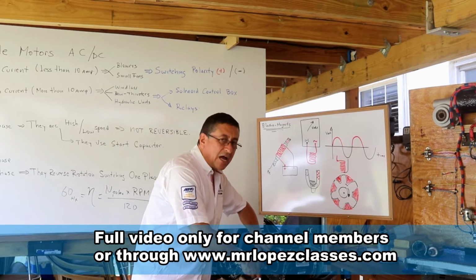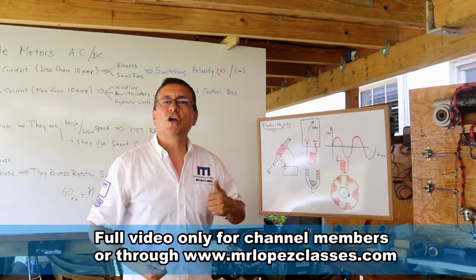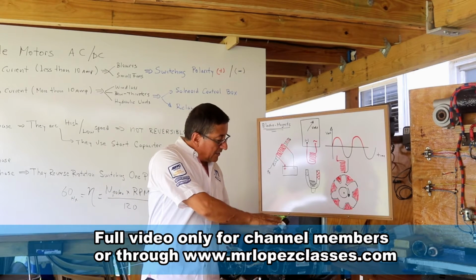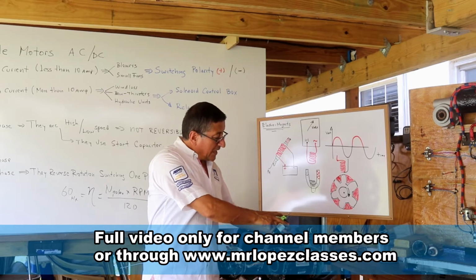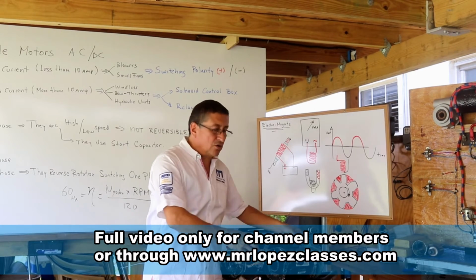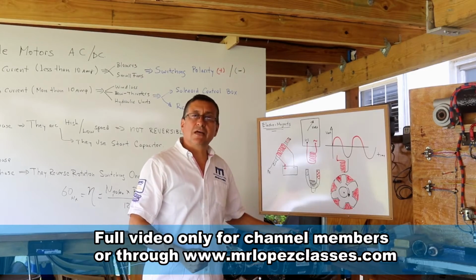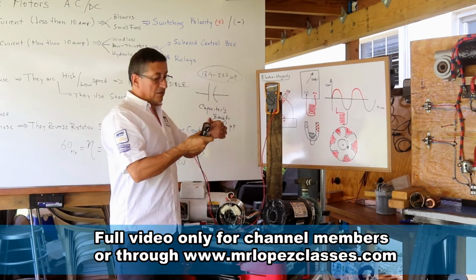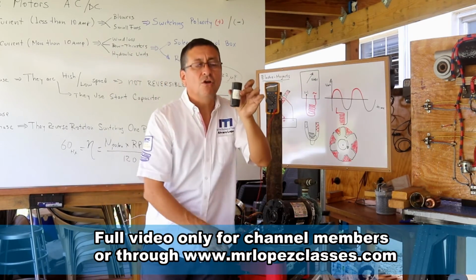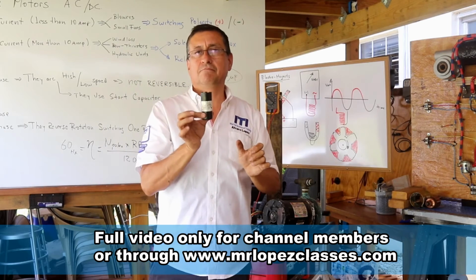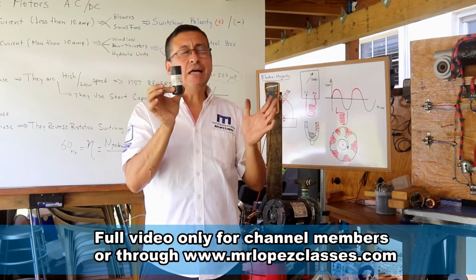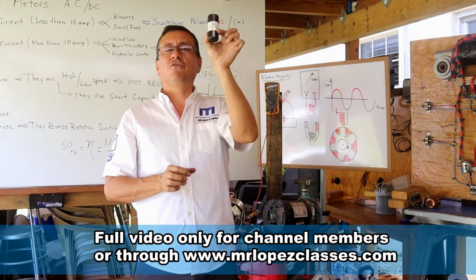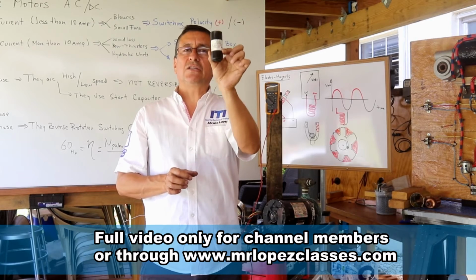Probably if you help it with your hand on the pulley, the motor continues running. If you remove the cover and check the capacitor, probably the capacitor is exploded, or too hot, or expanded because it is damaged. If the capacity is lower or higher than the range on the label, you need to replace the capacitor with another one exactly the same. Never less. A little more probably, but never less. I recommend replacing the capacitor with one with exactly the same characteristics.